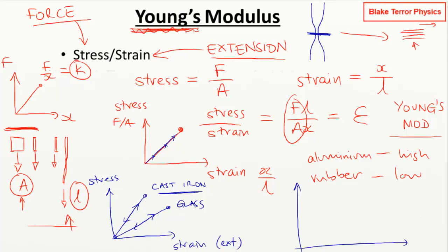And you get all manner of things going on in these stress strain graphs. So if this is our stress strain on a graph here, we've got our standard bit where we've got our Hookean elastic deformation. So this bit here is going to be the limit of our proportionality. This is where we've got proportionality between force and extension. So that bit, limit of proportionality.